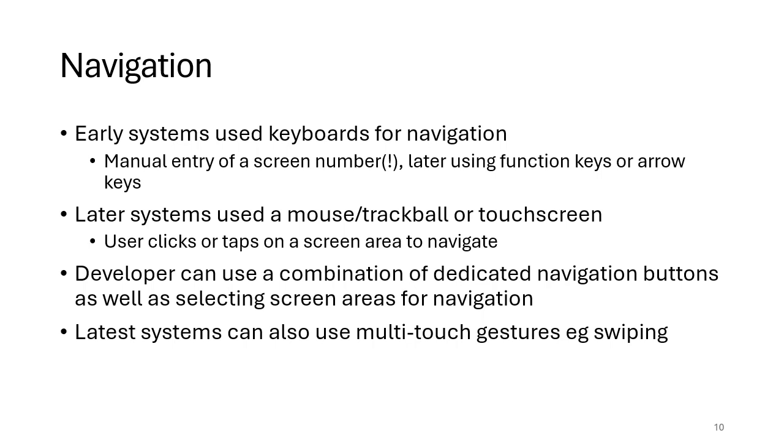So don't think of navigation as being an either or. There are multiple options you can use for navigation, including potentially a triple tap on a screen where the user enters or selects that screen number or that screen name. So don't restrict yourself to a single navigation mode. Different users will appreciate different ways of doing it, and giving them multiple opportunities is relatively straightforward in modern HMI systems.